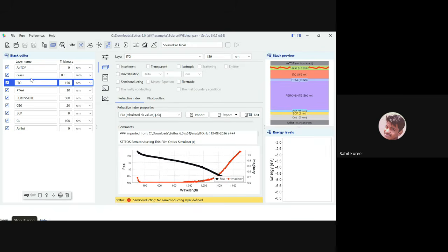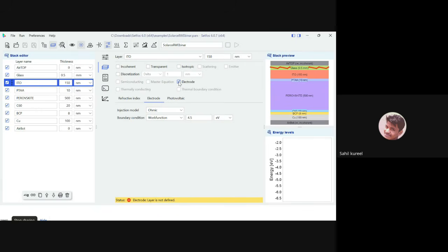So you can select the electrode work functions first. We are going to select ITO, but users who have their own project can choose differently. It depends on which type of electrode or active materials they want to select. They can use injection models like ohmic, thermionic, organic, which give the boundary conditions.